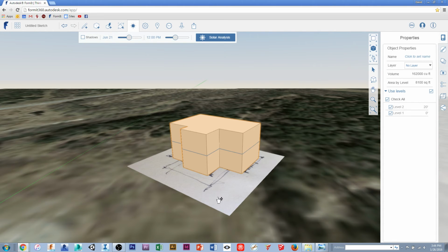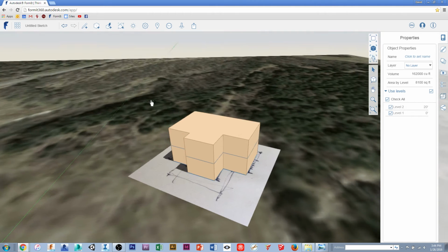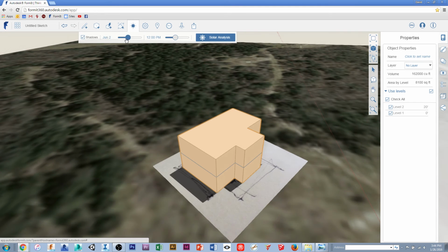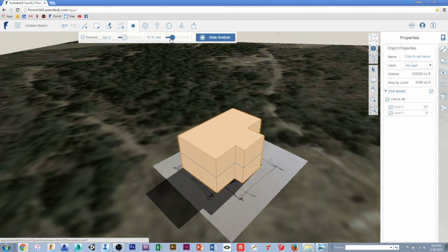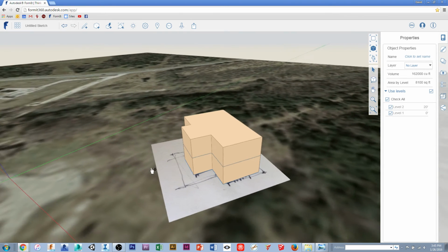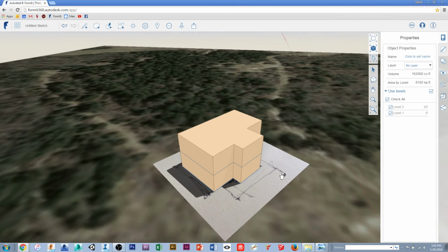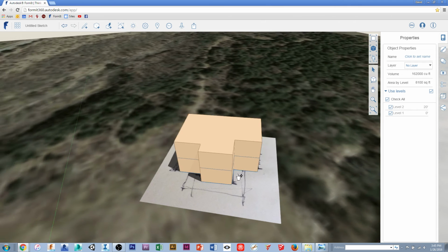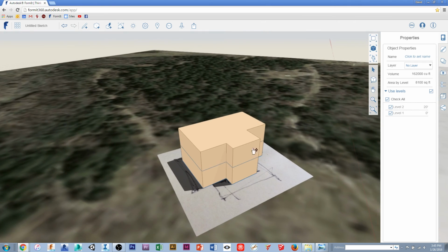So again, I've set a location, so I have my latitude and longitude. So I can be really precise in terms of my understanding with how the sun is going to work at any given date and any given time. So I know the temperature is going to be absolutely terrible on this site in early August. And I know at 1 p.m., if this is a whole lot of glass right here, it is not quite due south on the site, but I know I'm really going to need to do some work to make sure I'm protecting that elevation. It is not in any natural sort of shade at all.